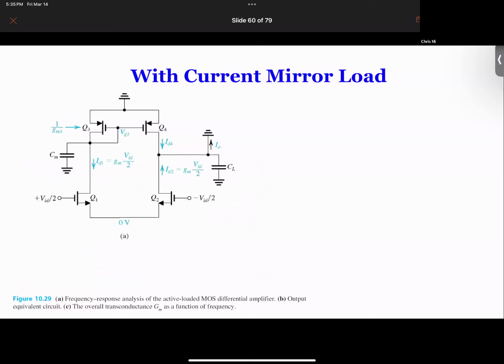So what happens is you amplify this pair, but you have those two there. And those two there are going to introduce additional capacitance like CM and CL, right? And of course, this is becoming a double-ended input to a single-ended output. Then we could, again, draw the small signal equivalent circuit, adding the capacitors of both transistors.